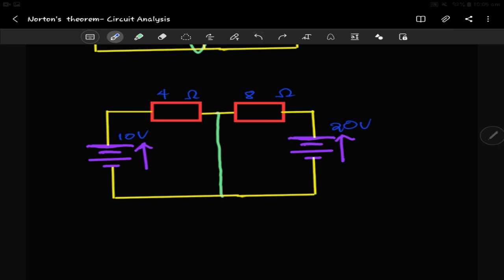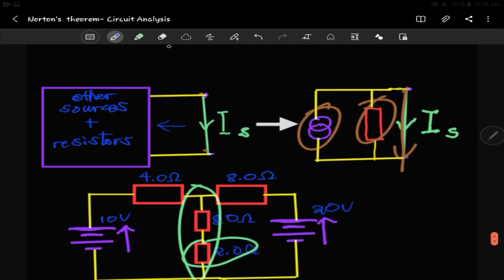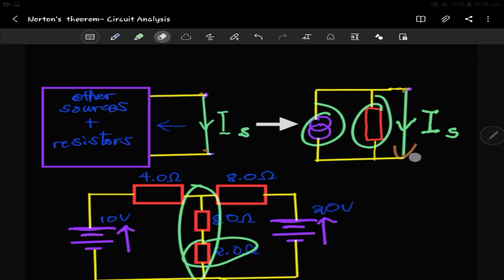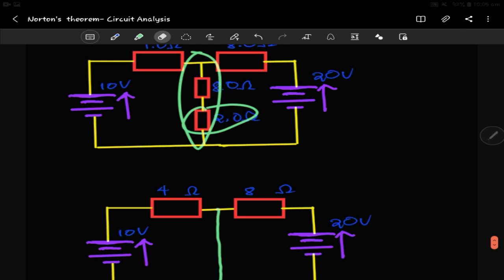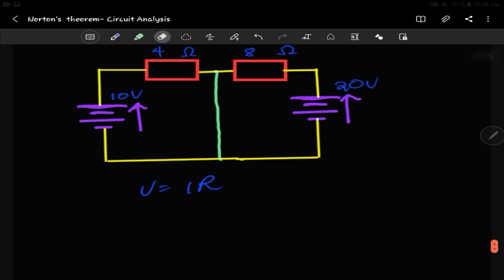Okay. Then again, when it comes to applied electricity, one of the basic equations is what? V is equal to what? IR, right? And then when we look at the Norton theorem, what did we say? That when we simplify it, what we end up with is a current source, or current generator, and then a resistor, right? And we've been saying so far that the easiest of these two to find is usually the resistance, right? So we are going to find the resistance for it.